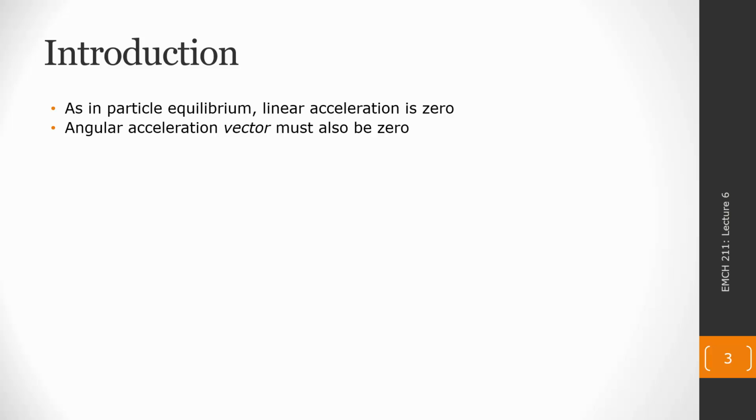And continuing what we saw for the 2D rigid body equilibrium, our angular accelerations must all be 0. What's new now is that in contrast to 2 dimensions, where we could only potentially have an angular acceleration around the z direction, in 3 dimensions we have to worry about having our angular accelerations around the x, the y, and the z axes all be 0.